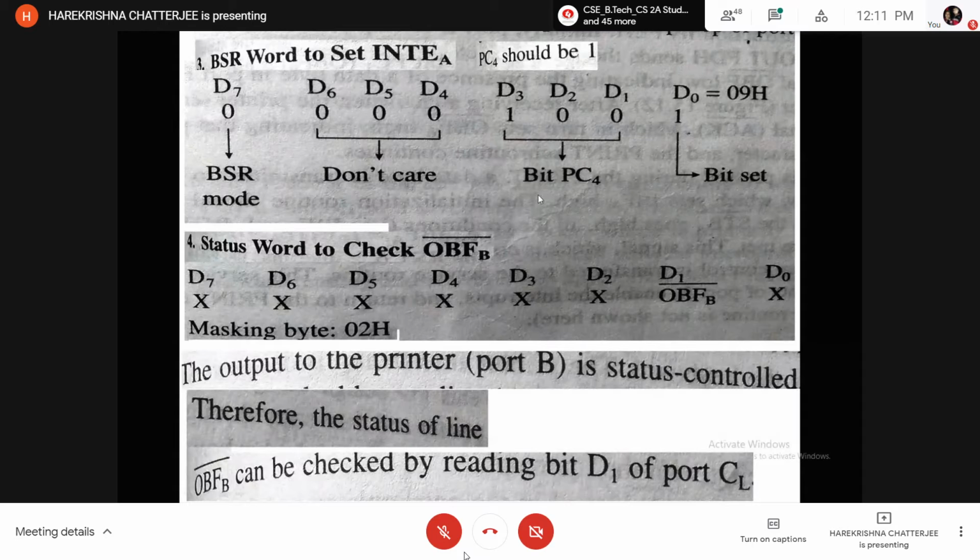So here the processor is going to read the keyboard data through an interrupt service routine when the 8255A interrupts the 8085 through RST 6.5, and then the processor will execute the corresponding interrupt service routine for reading keyboard data. Forget about that interrupt service routine.